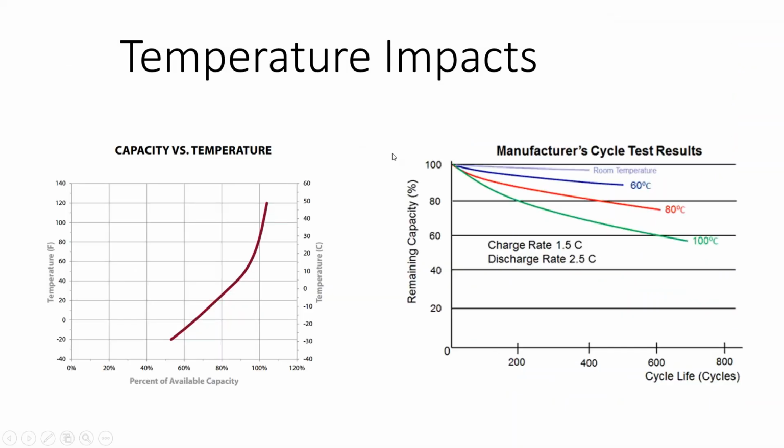Now, that said, cold temperatures, while they might result in less degradation of the battery, the colder the temperature goes, the battery shrinks in capacity as well. In fact, with flooded lead acid batteries, if you get below freezing temperatures, you have to keep them at least 50% charged, or else the electrolyte begins to freeze.